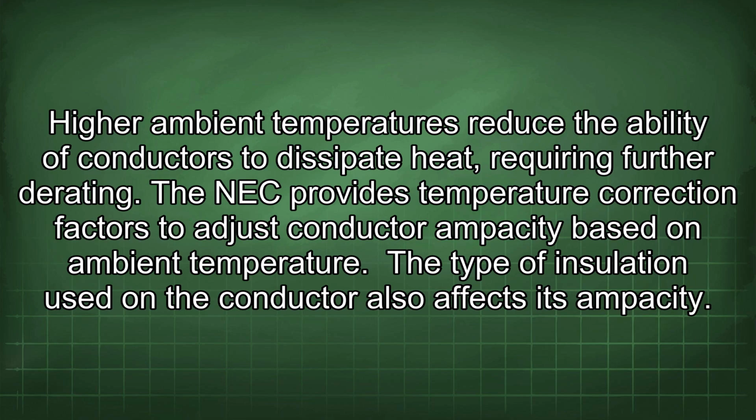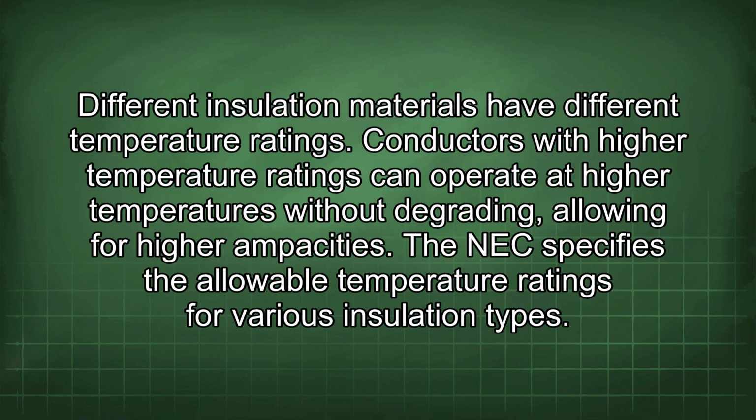The type of insulation used on the conductor also affects its ampacity. Different insulation materials have different temperature ratings. Conductors with higher temperature ratings can operate at higher temperatures without degrading, allowing for higher ampacities. The NEC specifies the allowable temperature ratings for various insulation types.